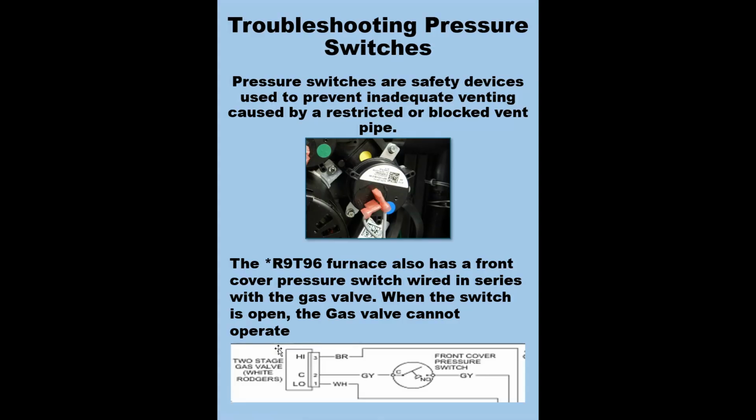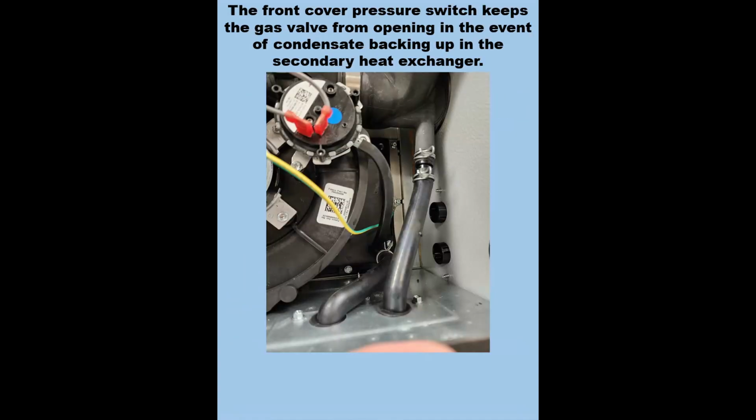And the AOG R9T96 furnace also has a front cover pressure switch wired in series with the gas valve. When the switch is open, the gas valve cannot open. The front cover pressure switch keeps the gas valve from opening in the event of condensate backing up in the secondary heat exchanger.